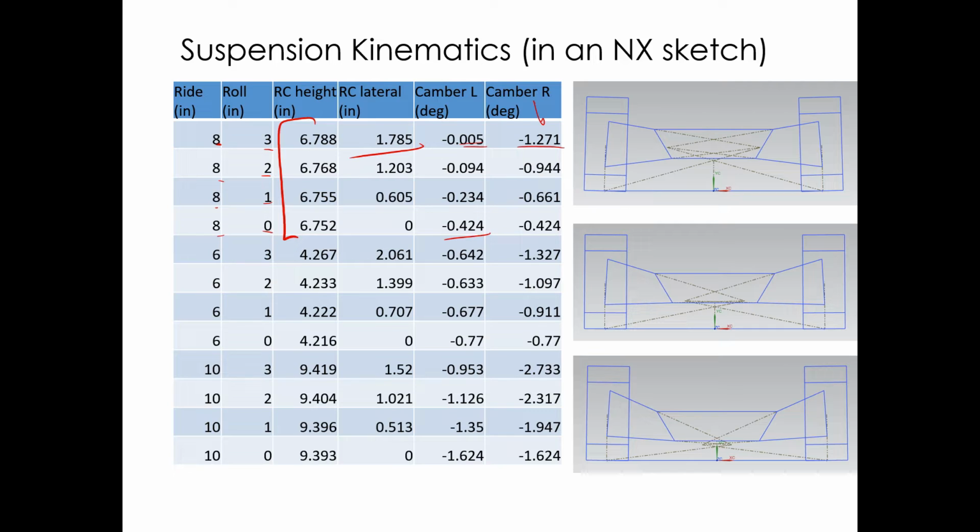So the camber control is good, the roll center migration is good. When I bump the chassis down 2 inches, you'll see that this changes by somewhere around 2 inches. It's a little more than that, but we're still within the fist rule here, so it's fine. So bump and roll, our roll center only migrates 2 inches, so we're good on that. Our camber control is good. All of our tires are tipped the right way.